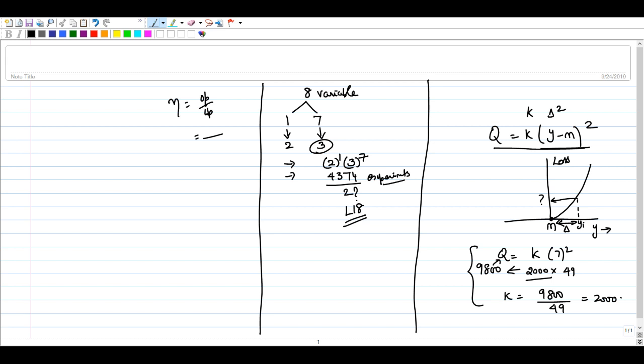Whatever material the part is made of, the screw can also be made. Hence the second criterion will be violated. Therefore, a screw or any fastener cannot be considered as a theoretical minimum number of part. So that's how one calculates the theoretical minimum number of parts in an assembly. I hope your question is answered, Varshal.